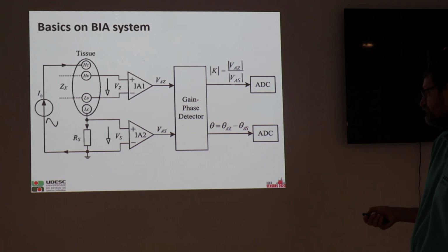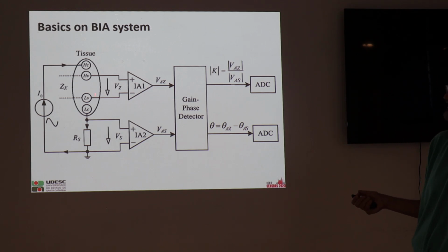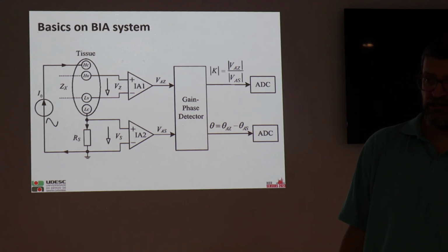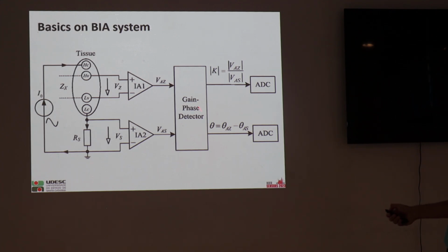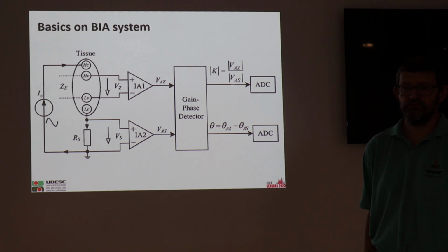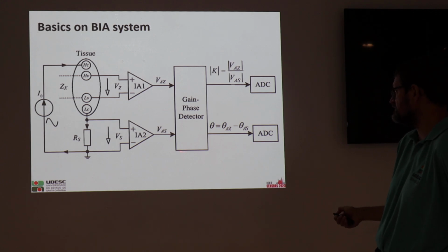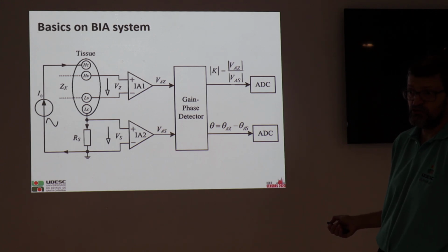But also, if you don't want that, you can design your own system. You just need a current, a signal excitation and a measuring system. And you just need to buy some chips. For example, AD5940, one device which is a phase analyzer straight away, just to power on.